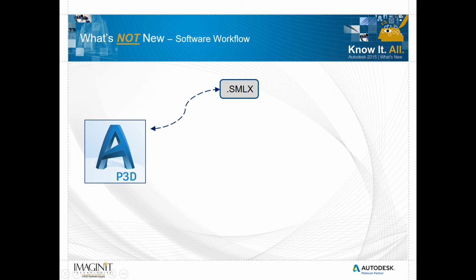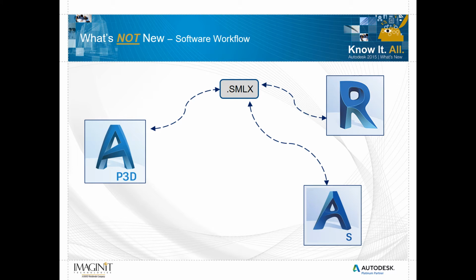Now, once I launch that button, I can then choose to share it with either Revit or inside of Advanced Steel to do my detailing for my structural work. Now, because Advanced Steel and Plant 3D are a DWG file, utilizing AutoCAD functionality, I can then choose just to simply use an XREF and XREF in that detailed structural model into my Plant 3D.